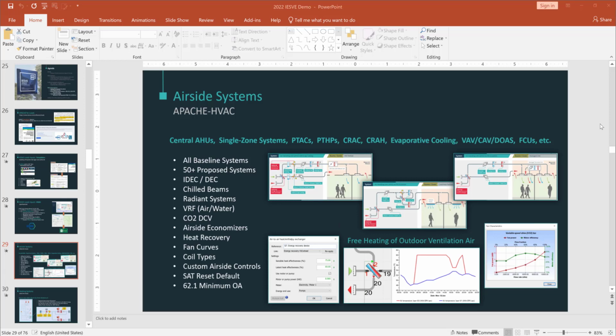That's a really good question, because of the versions of ASHRAE that you used. ASHRAE 90.1 2016 has been sold as a stable baseline model, if of course you're using the performance rating method. The only thing that's supposed to change is the building performance factors, because it's supposed to have a stable baseline, which really only means you're making edits to one model.